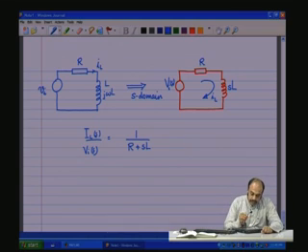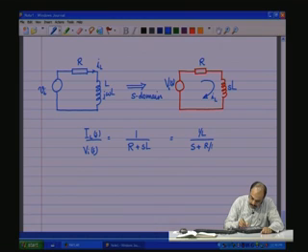So, the voltage divided by this is the system which gives you, if I rearrange the terms, 1 by L divided by S plus R by L. Here also notice that there is only a scaling factor in the numerator, there is no function of S in the numerator, and therefore, there are no zeros.